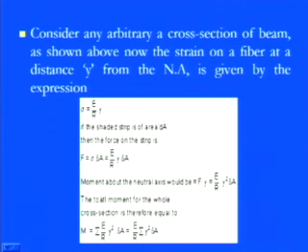But now if we sum up all those small elements, each at a certain distance from the neutral axis, we get the total moment applied on that particular section, and due to that we have the bending stresses. So the total bending moment over the cross section is the summation of E by R y square dA.